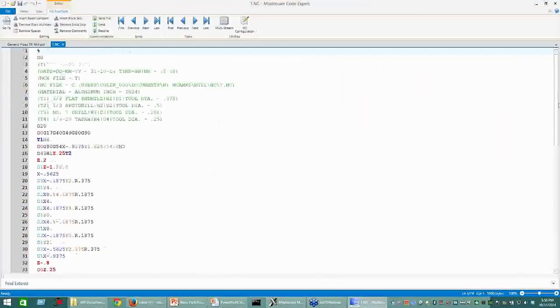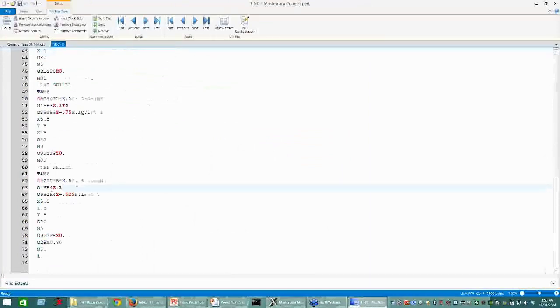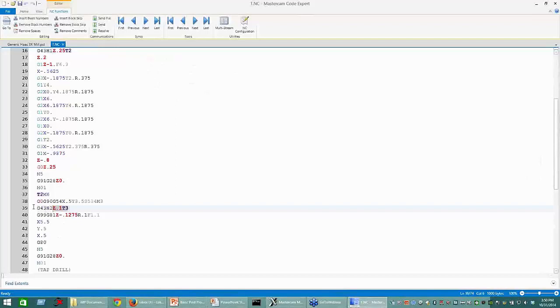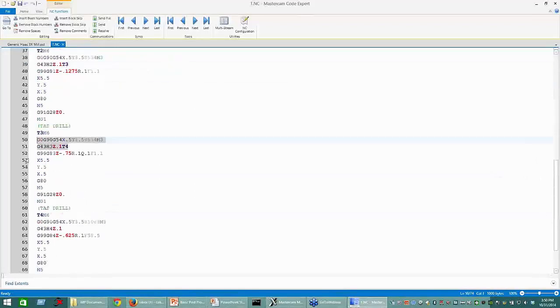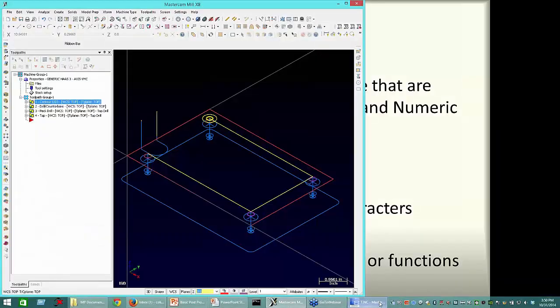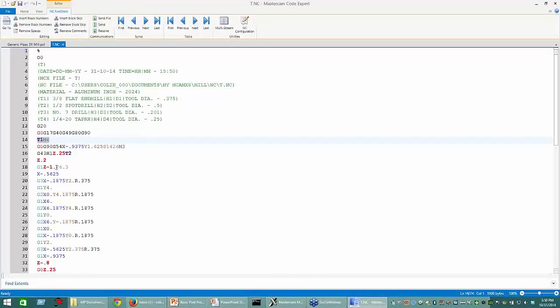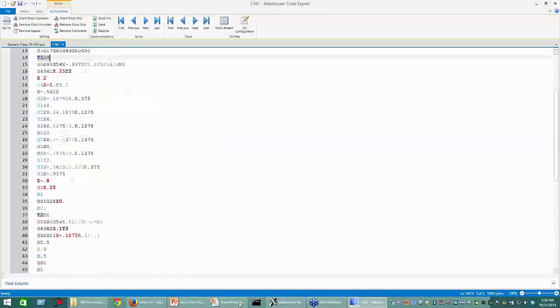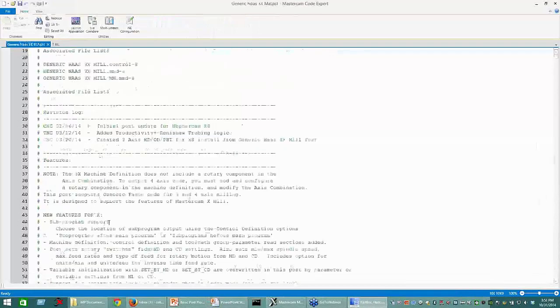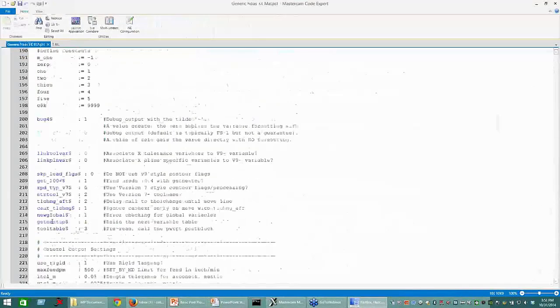By turning that setting to a 0 instead of a 1, we removed the tool staging, but only at the last tool. So you can see that we've got tool staging on here after this tool change, same here, but at the last tool change, we're not staging the first tool. So if I go back in there and look at that actual tool change call here, you want to be able to reset your machine, shut it down for the night, and you don't care if this is staged or not, because you know it's going to change to tool 1 and not a different one. We also, if I go back to the post, let's go back and look at this setting for tool staging.